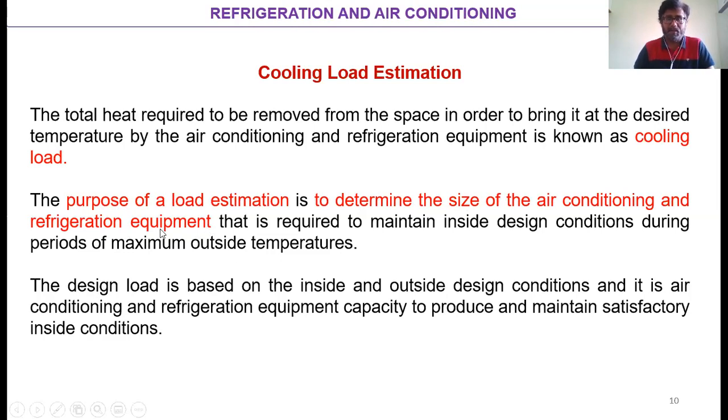Size of the equipment means that I should take into consideration the design of a compressor. The compressor shouldn't be too bulky, nor too small, too tiny, so that it won't be working according to the requirements. And the sizing of the condenser, then the sizing of the evaporator, then the sizing of the control equipment, that is the expansion devices like the capillary tube and the thermostatic expansion valve. So all the sizing of this equipment would essentially depend upon how effectively or how accurately you can calculate the cooling load.